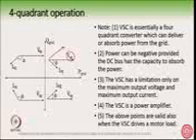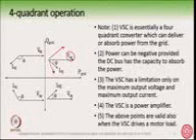So the VSC is essentially a 4 quadrant converter which can deliver or absorb power from the grid. We can see here that we can place the output voltage from the converter with respect to VAG, here or here, greater in magnitude or lesser in magnitude, like a synchronous machine connected to the infinite bus bar. You have an E, that is the back EMF, and you have a V, which is the infinite bus bar voltage, and E and V can be leading or lagging, and E can be greater or lesser in magnitude compared to V, and accordingly you will move in the 4 quadrants of the PQ diagram.